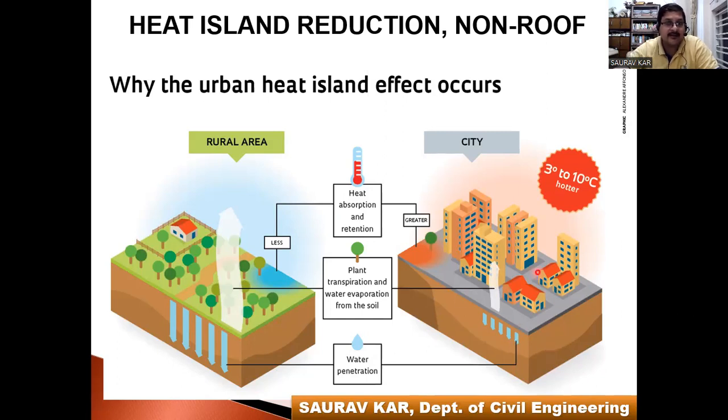The biggest problem here, since in cities the majority of the surface is paved either with bitumen or concrete, is that water percolation to the groundwater, underground, is not possible. That is why the biggest problem in urban cities is that the groundwater is not recharged. If you go deep down for boring, you will not find water. The majority of rainfall goes through surface or storm runoff or drainage, but not through the natural soil of the earth.